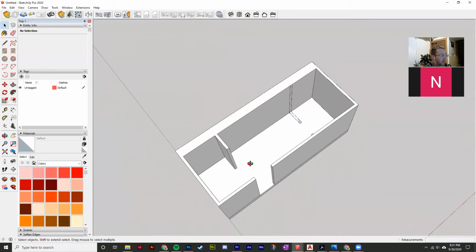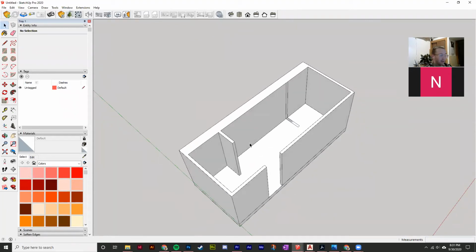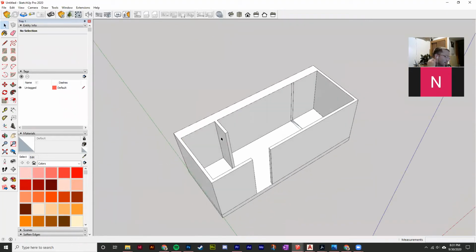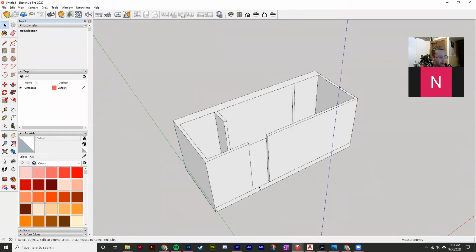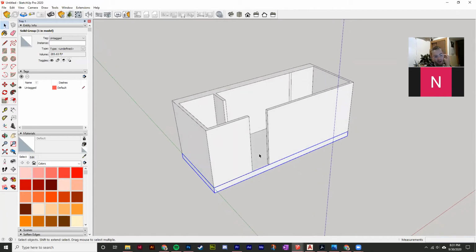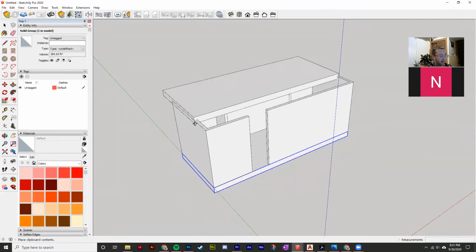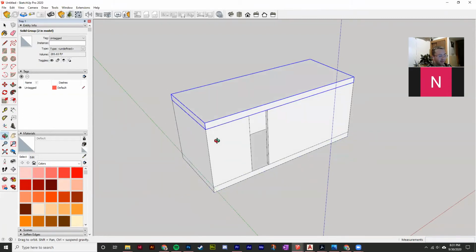And then to show you how to do the layers, I will also do a ceiling plane, and I'll also show you how to copy. So my ceiling plane is essentially the same as my floor plane. So I'll just make a copy of that. Of course, you can do Control or Command C and Control or Command V. So I'll do that now. Control C, Command V, and that'll give me this, and I can easily place it on top.